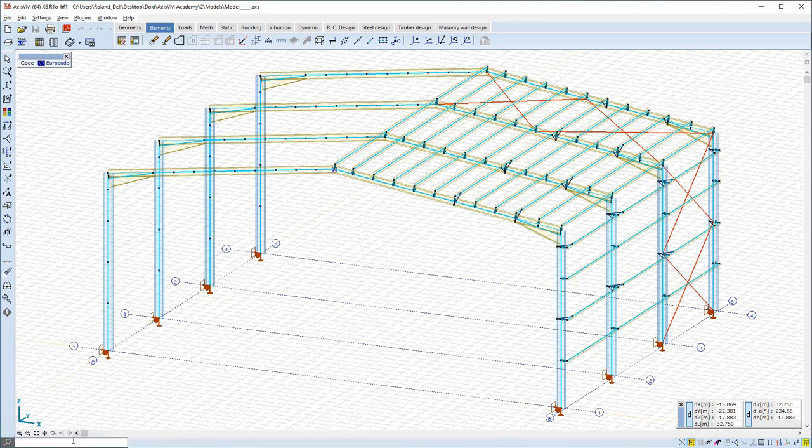Multiple criteria selections can even be used for selections based on the results after the analysis is performed, so we can make selections of members with specific cross-section, length or material, where a certain type of result component has its maximum value. To start a selection, the star sign has to be typed. Pressing Enter without specifying anything else will select everything in the model. If typing a minus sign after this, everything will be removed from the selection.